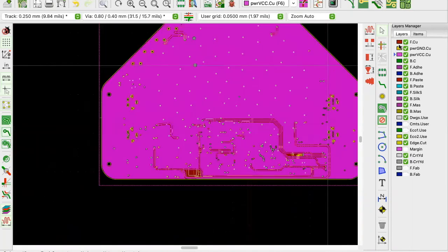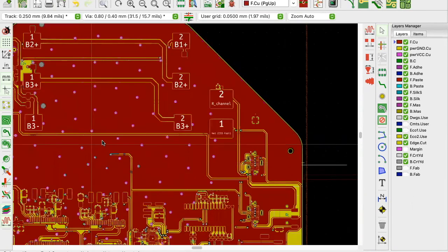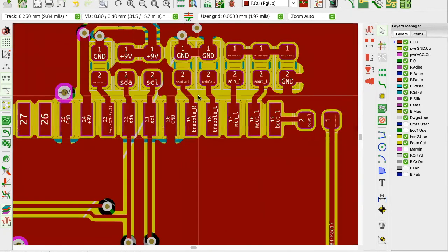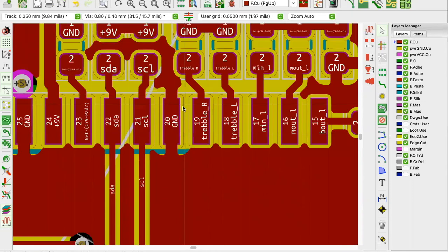Your solder mask will always be on the top. It pours in between these traces, so that when we are talking about solder bridges, you find that at times these traces or pads are very close. And when we are soldering, solder might bridge or overflow to the other pad, shorting it.